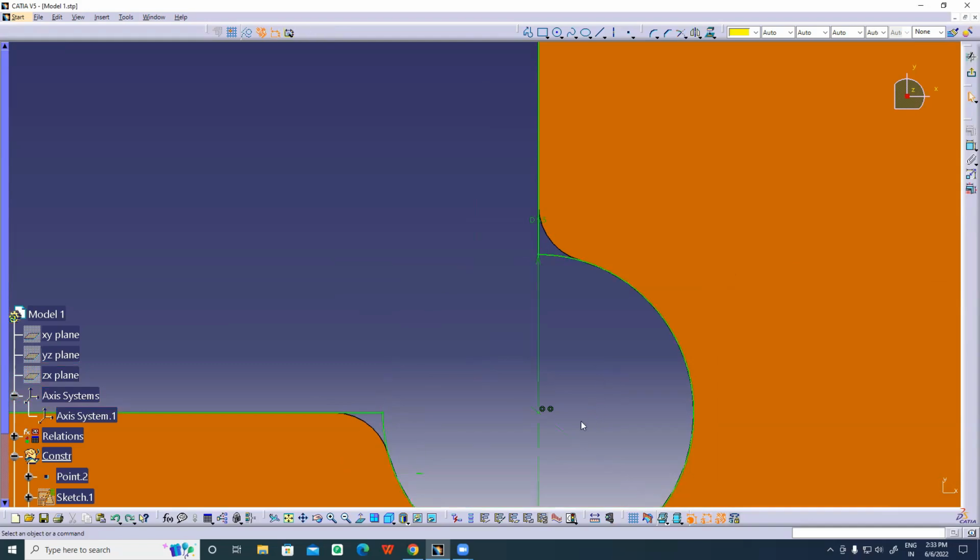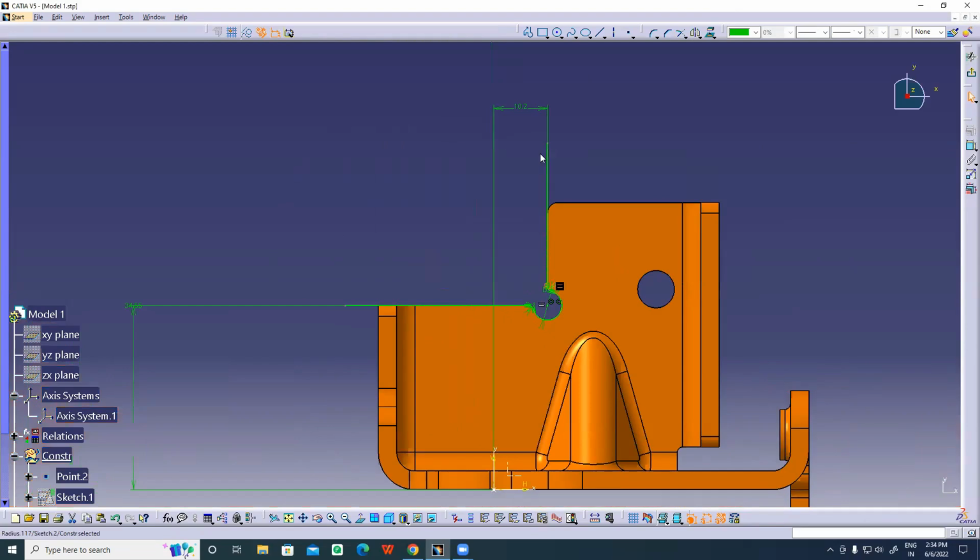Sorry, I was in a trim. I didn't exit it. So pressed the escape key, so exited from the trim tool, selecting the two edges, and now applying a fillet and changing the value to 1 mm. Okay, after that, now you can see the length is not defined completely, right? So I don't need to define the length.